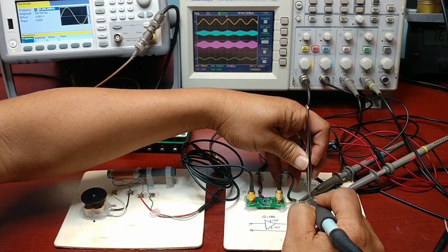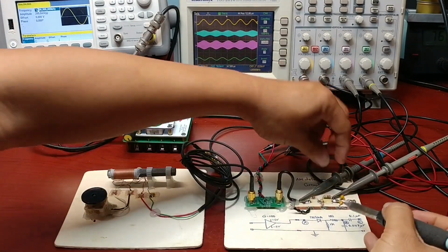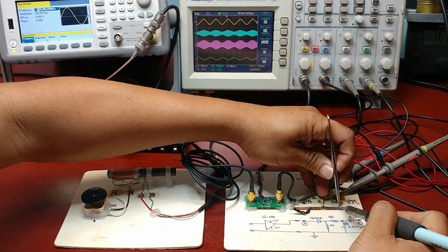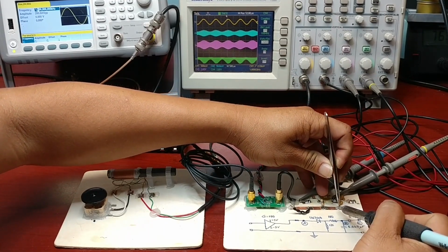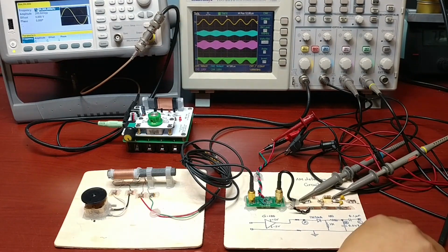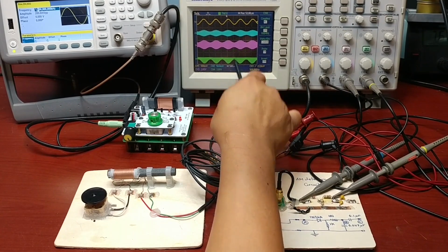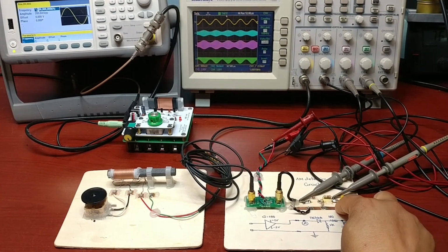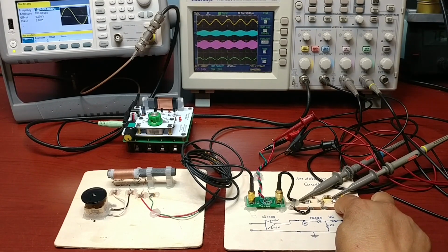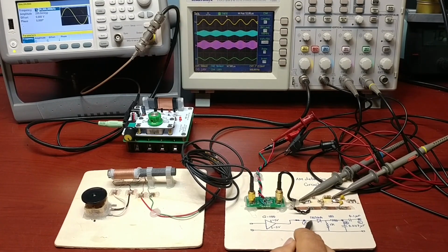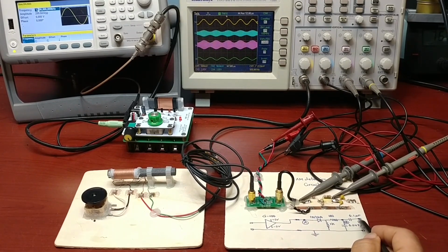And we need the amplifier to have a little higher gain. I now remove the filter capacitor to see the signal. As you saw earlier, the diode was mounted in another direction. The AM signal is chopped off the bottom half. Now we change the diode direction. The signal is chopped off the top half. Connecting the filter capacitor, the high frequency is filtered out, yielding a 1 kHz sine wave signal output. Placing a diode in this direction or the reverse direction, the signal output is 180 degrees out of phase. However, the sound we hear is the same.